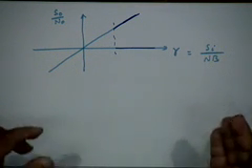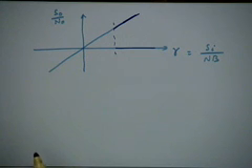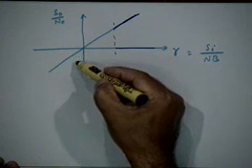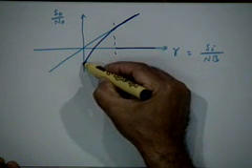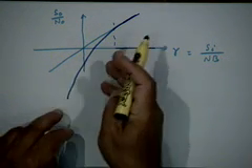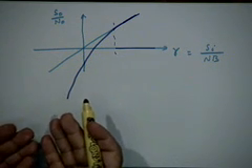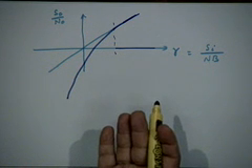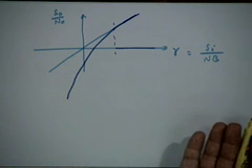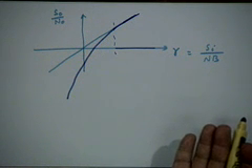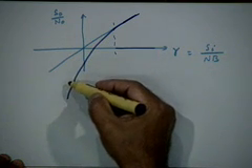However, the moment you fall below a certain input signal to noise ratio, when the input signal becomes weaker than some value, you start deviating from the straight line curve, right, and you start moving down. Eventually, at lower SNRs, we get an output which does not resemble the input at all in terms of message, right. So you get a curve like that.